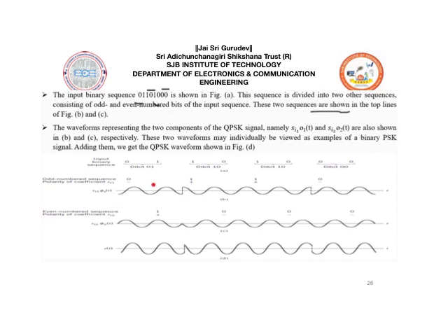In the odd numbered sequence we are taking 0 1 1 0. It means this 0 is an odd numbered bit, 1 is odd numbered, again 1 is odd numbered, again 0 is odd numbered. Those we are taking here, and the polarity of the coefficient x I 1 is considered. It is multiplied with the basis function phi 1 of t.